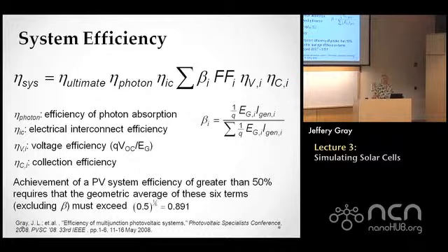Fill factor is the same as our fill factor, as you already know, but instead of looking at open circuit voltage, we look at the voltage efficiency, which is the ratio of the open circuit voltage to the band gap. So its efficiency would be 1 if we could somehow get to the band gap voltage. And when you look at this equation and stick in typical numbers, what sticks out at you is that this ratio is